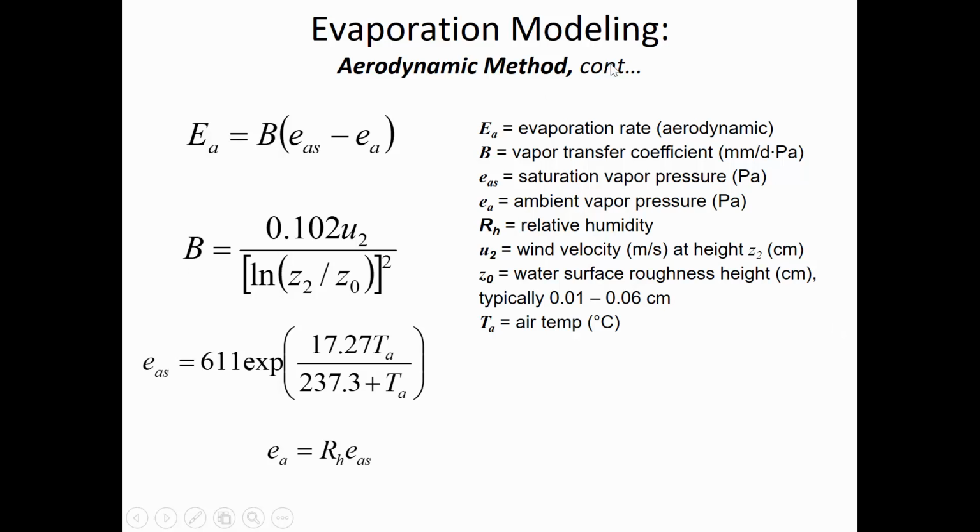All right, so here's the approach we're going to go through. We have to estimate the saturation vapor pressure, and the saturation vapor pressure is going to be given, but then the ambient vapor pressure we multiply by the relative humidity. And the example that we're working, the humidity of 75%, that's pretty high. It would be unusually humid, but maybe not out of the realm of possibility. Basically, the procedure we'll go in is, based on the temperature of the air, estimate the saturation vapor pressure, then we find the ambient vapor pressure.